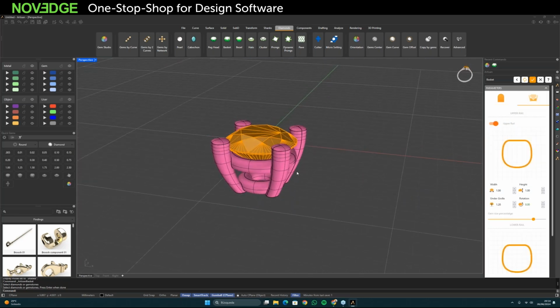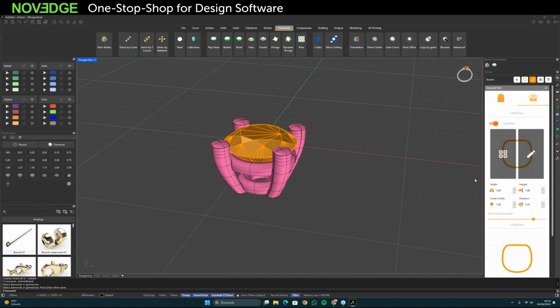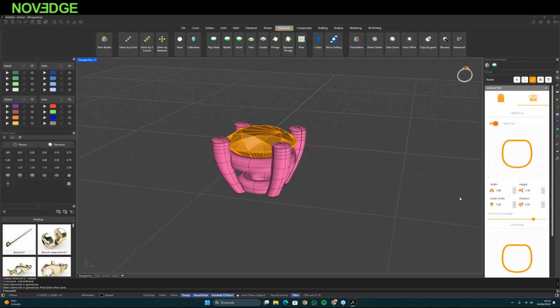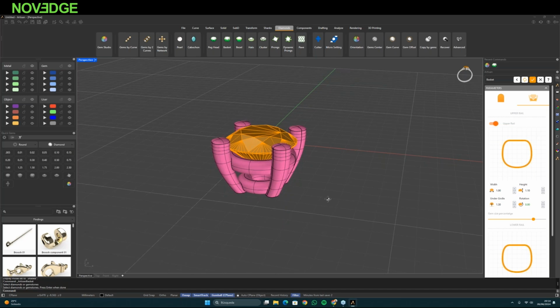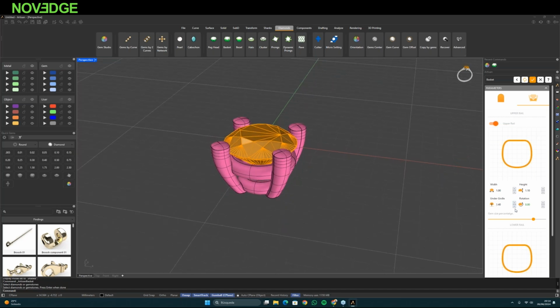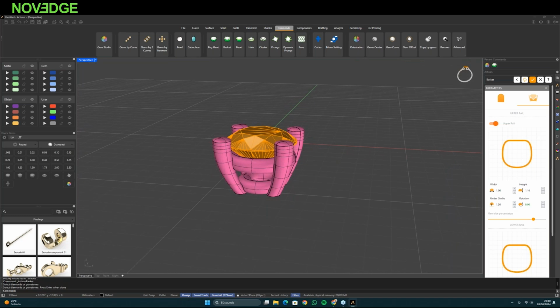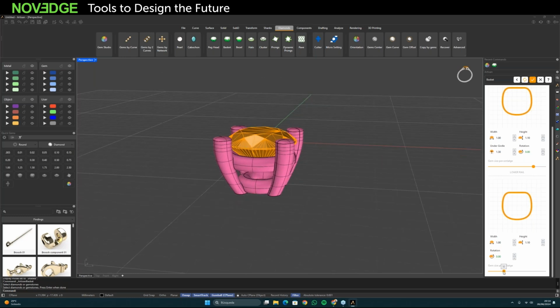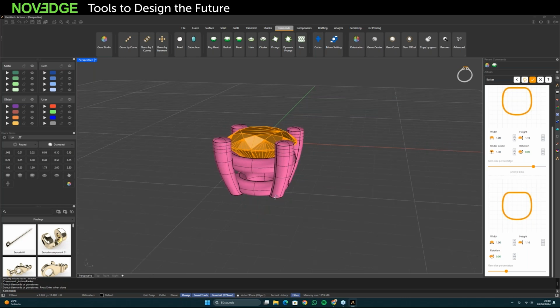For the prongs, let's change the rails. And for the upper rail, I'm going to increase the thickness a little bit and put it a little bit lower from the girdle of the stone. Okay, 1.3, 1.4, no, 1.3, it's okay. And for the lower rail, I'm going to do the same. I'm going to increase the section and increase the diameter like this.